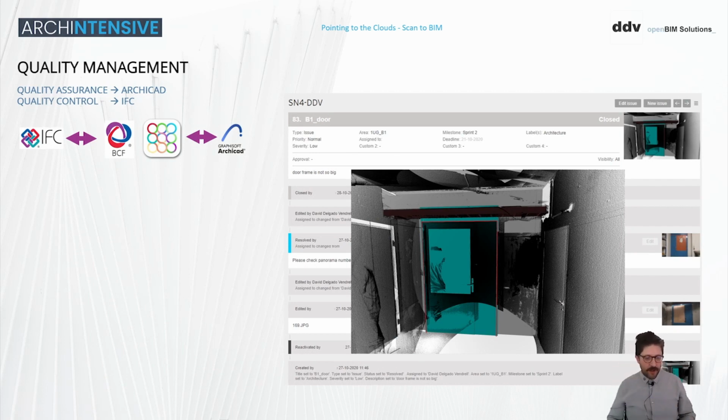We are using an issue tracking platform because we are applying the openBIM approach here, using the BIM collaboration format as our way to communicate the issues that we as the modelers are fixing, from the ones that our client is detecting or sending us new requirements or some things that we should fix once we are delivering in our intermediate deliveries.